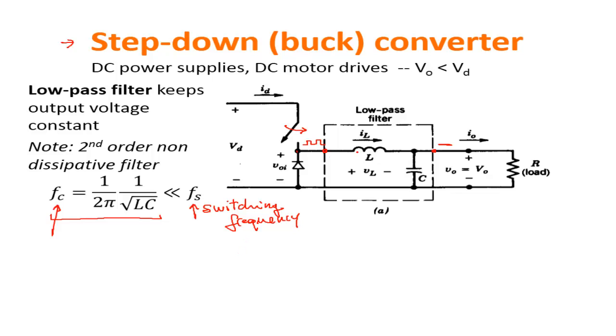The other important difference with respect to the ideal situation that we have discussed earlier is this diode. You have just to consider what's the role of this diode. This diode has the role of putting this node to almost 0 when the switch is off, because when the switch is on, you have current flowing in this way through the inductor, right?